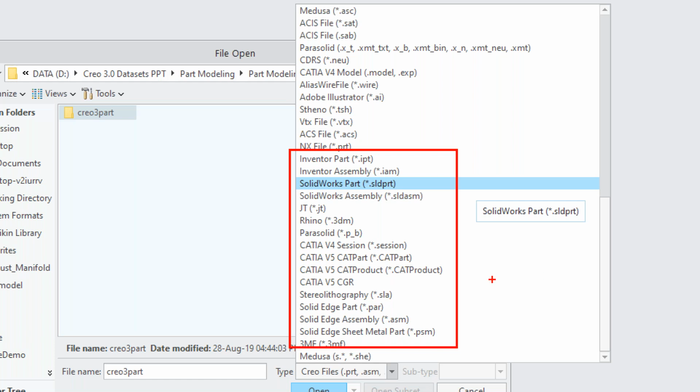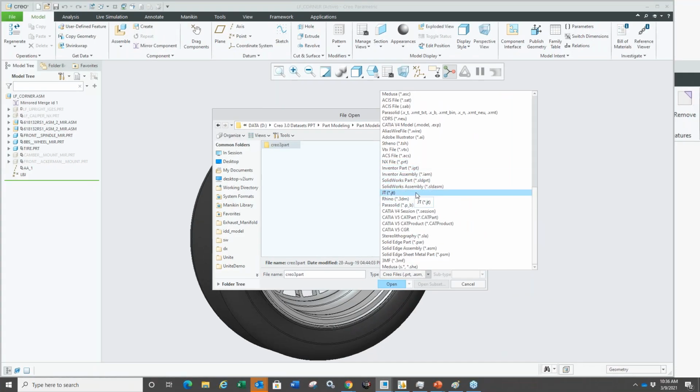Now, we strongly encourage trying out the native file compared to the STEP or IGES, and I'll explain more about why. As a general best practice, your chances of getting the data through are higher when you use a native file instead of having SolidWorks export a STEP or an IGES that I then import into Creo. It's almost like using a middleman here, and data gets lost both times, as they export and as I import. So if they are willing to give the native file, it's good practice to use that directly, because we can do that starting with Creo 3.